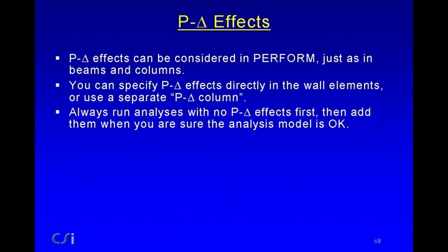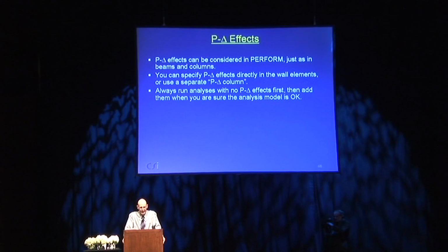So other aspects, P-delta effects. You can consider P-delta effects in walls in Perform just as in beams and columns. When you have wall elements, you just say whether or not you want P-delta effects to be included. Or alternatively, you could use a separate P-delta column. If you're not familiar with this, don't worry, it's just another way of accounting for P-delta effects.